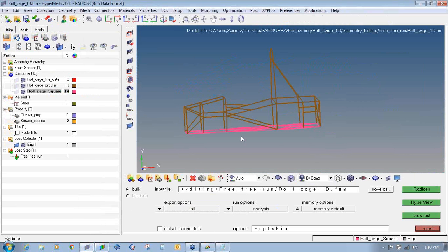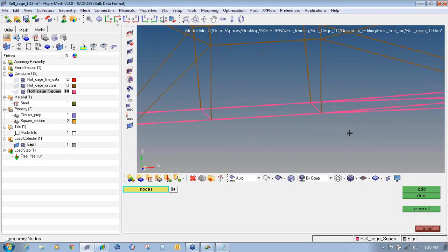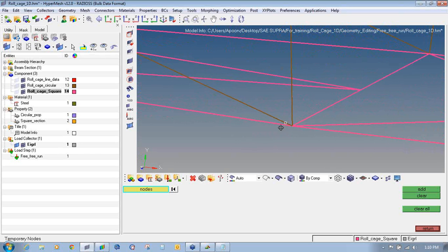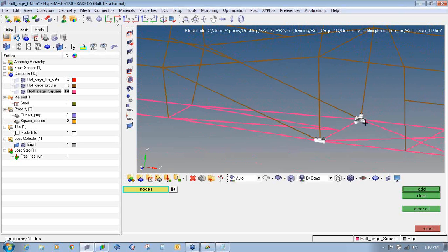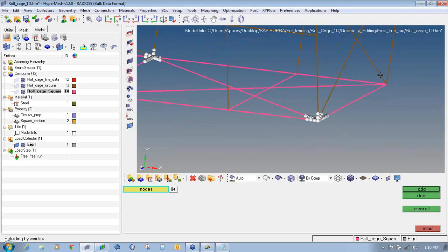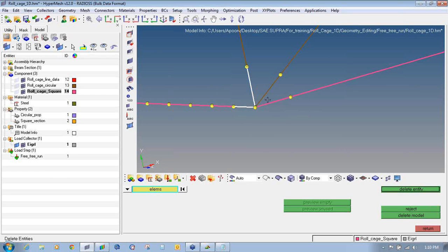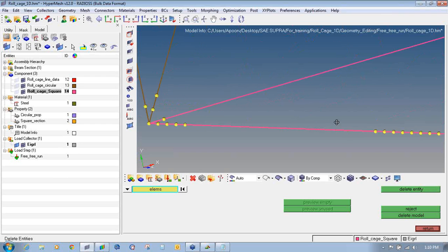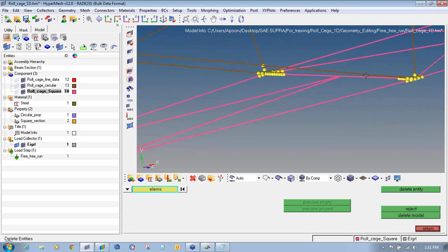Again go to HyperMesh. So these are not properly connected. Press Shift F2, add these nodes. I will show you the other way now. The first way is to create and join the lines, and the other way is you can directly join the meshing. So these are the areas where the meshing is not properly connected. Similarly, add the nodes, delete those elements, and create new elements, same as the free 1D which we have done for free 1Ds.